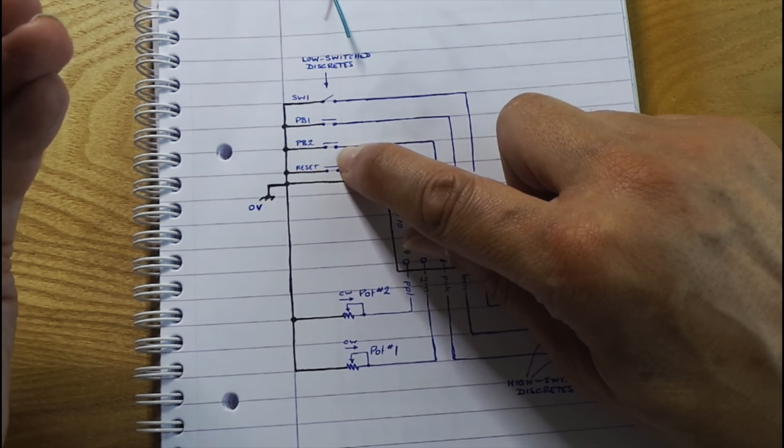Let's continue then and take a look at the second of the JST connectors, this 20-way connector. Now this connector is for inputs which are specific to module DM3, as opposed to this one, which is generic and the same on all modules. So this one then, again, it's a 20-way connector, and it has a similar kind of connector but just bigger, and it has the same arrangement where this little locking tab is at the top, and you push down here to open that, and push it in, and it will snap into position. So let's go through the connections on this one then.